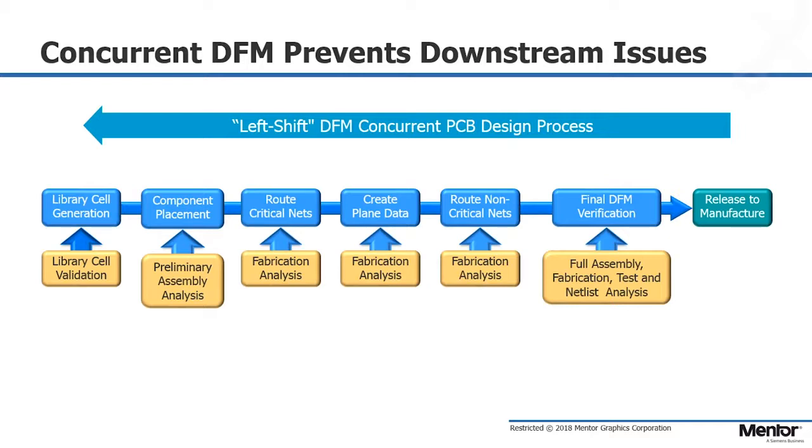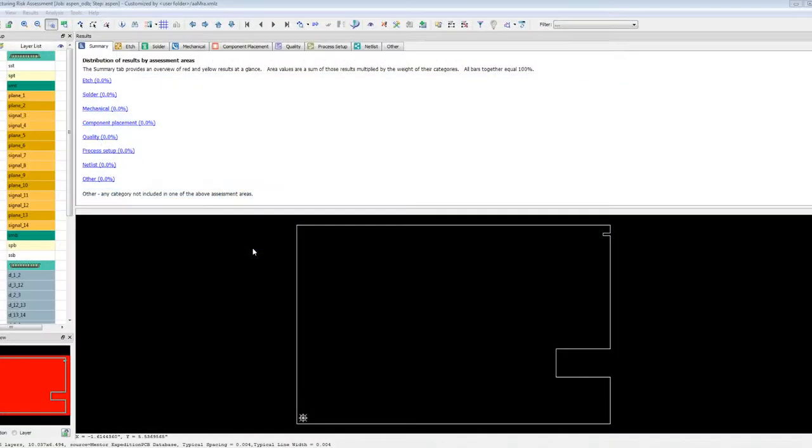With PCB design for manufacturing, best practices are to perform DFM concurrent with the PCB layout process. That is why we have developed a Valor NPI DFM analysis add-in for Expedition. This allows the designer to get access to DFM analysis in an environment they are accustomed to using. There is no training required or different software tools to learn. The setup of the DFM rules is easily managed from the Valor NPI application.